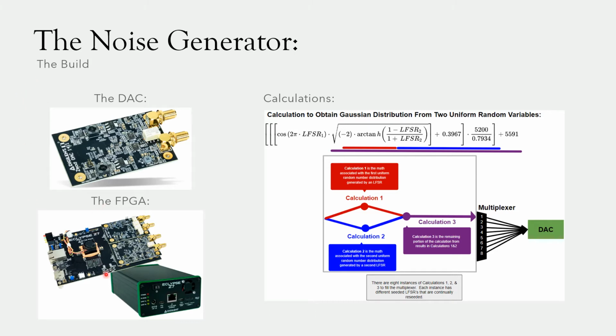This output is done by the DAC. The DAC, you can see, plugs into the FPGA board. A useful feature of this FPGA board is you can have two DACs. This means one can output signals that we know will fail the test, and the other can output signals that should pass the test. This gives GE added options in their debugging capabilities. It also comes in a nice enclosure, which is a little bit more noise proof than having just a bare PCB board, and looks nice.